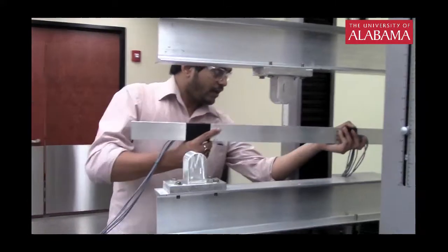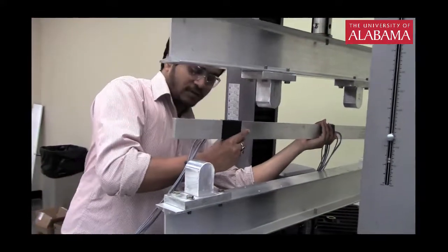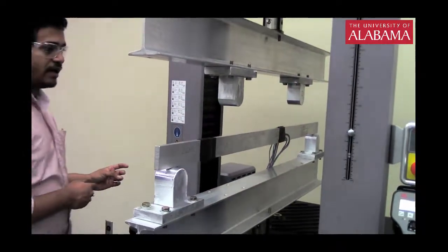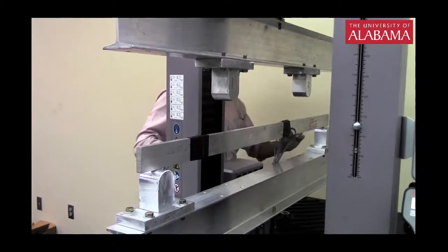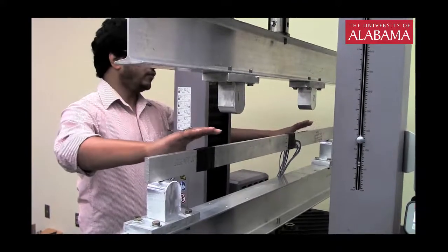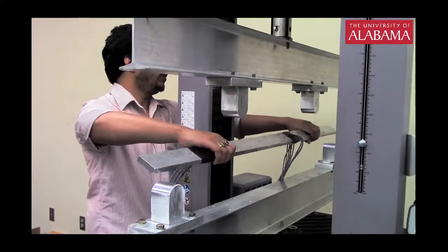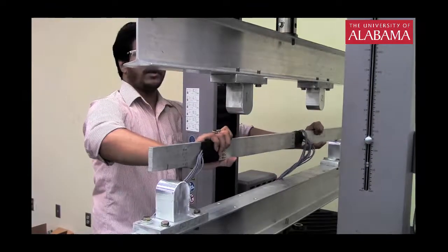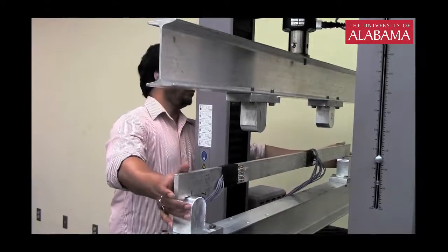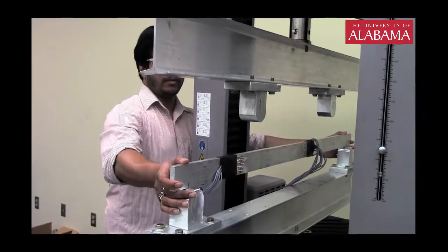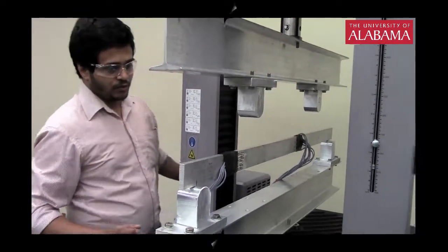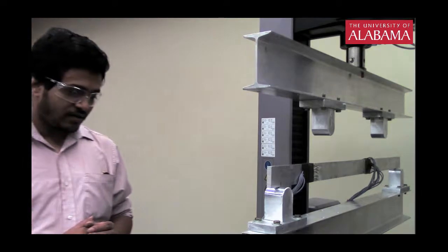Okay, so firstly just take this beam and place it on the supports very gently. Place it on the supports very gently, and then we will see whether this beam is positioned properly. So this is the bottom part of the beam, so I need to flip it. So basically you just flip it, and the top and the bottom are mentioned over here. It's written with the help of a marker, so you can readily look at it. Okay, once you position the beam, make sure that it is symmetric. So right now the beam is set into place.